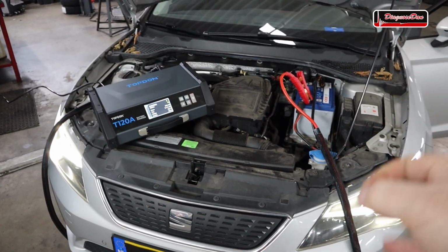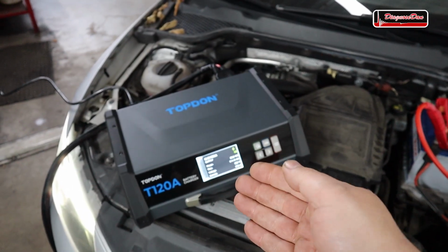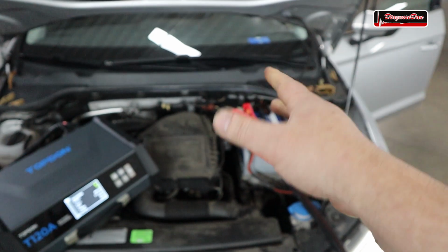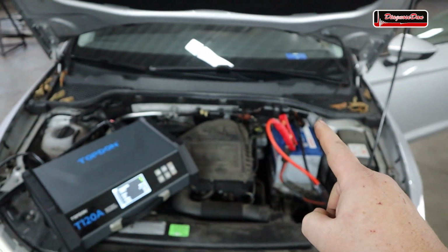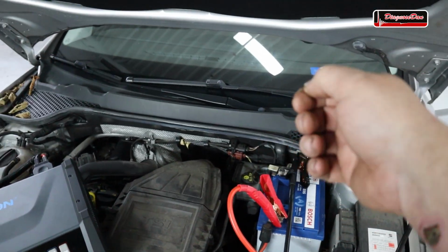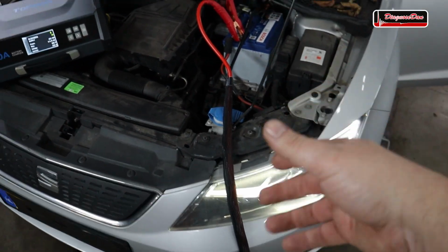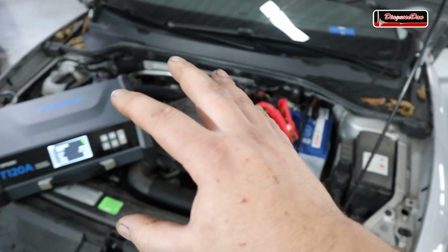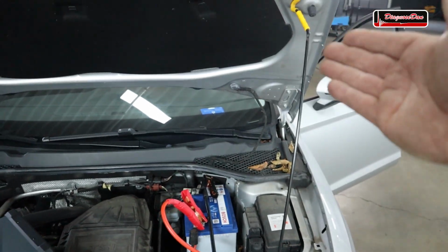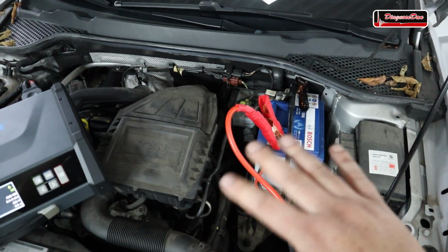Now, as you all know, when I'm diagnosing a vehicle, I always like to hook up a battery charger. Why do I do that? First of all, when we're diagnosing a vehicle, the ignition probably needs to be on for quite some time. We need to do some measurements, we need to read fault codes, and I don't want to worry about the battery draining. When you turn on the ignition on a modern vehicle, normally the lights come on automatically and that will drain your battery. I don't want to return this vehicle to the customer with an empty battery after we have fixed his window. So let's say we fix the window, but then when the customer comes home, it doesn't start anymore. We cannot have any of that.